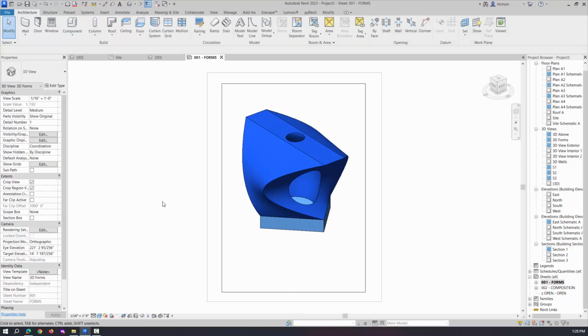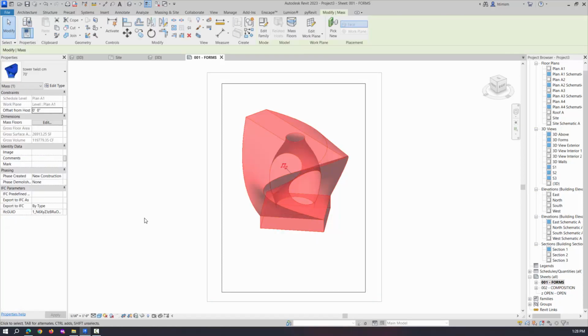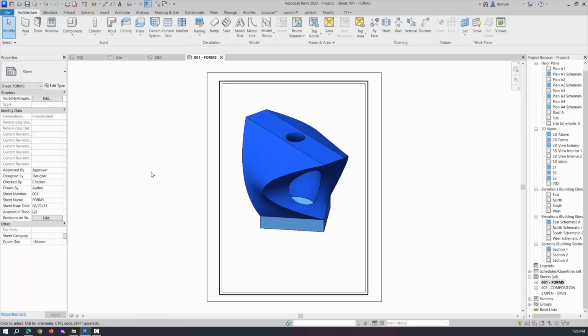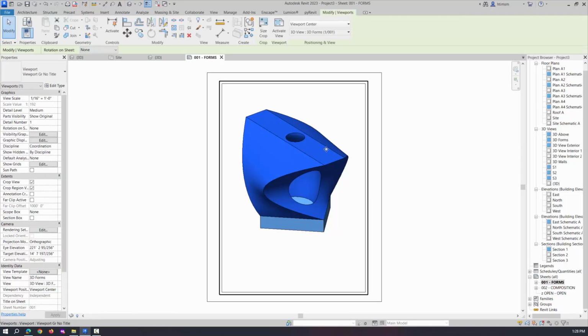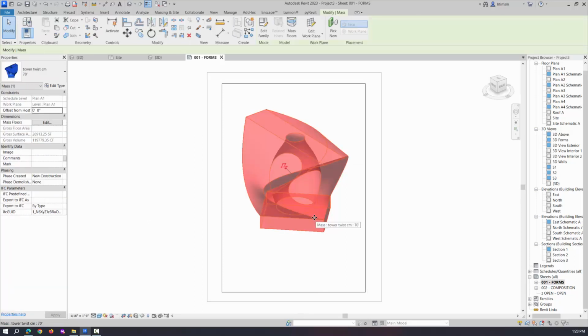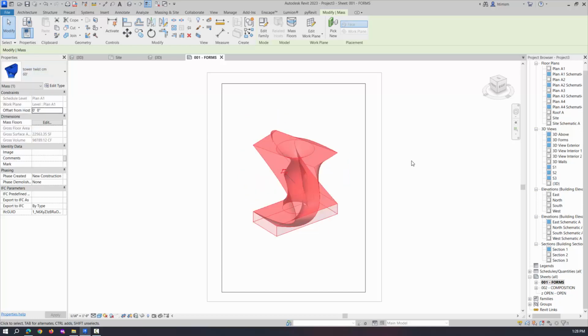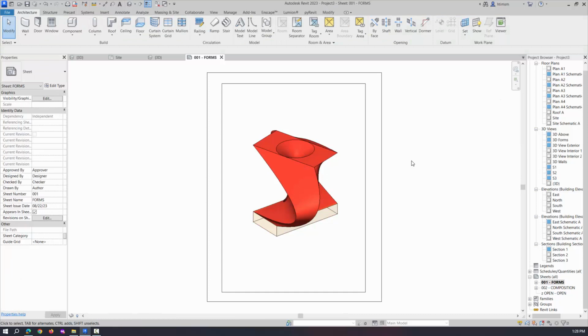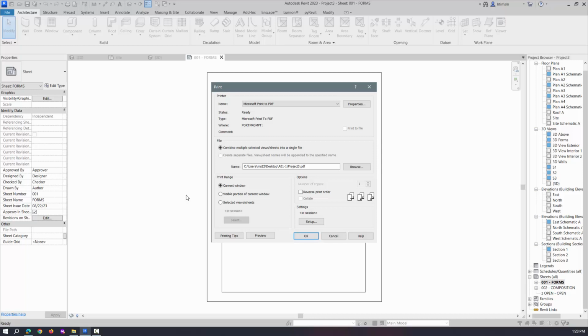So then you will double click. So I'm double clicking inside this window, right? It's activating and allowing me to select that form. If I double click outside the window, it puts me in sheet view and I can't select that form. So double clicking activates that view, allows me to pick the form and flip it out for my other type. So I'll flip this out for the 60, right? And double click outside and then Control P again and just repeat that process to print that guy, okay?